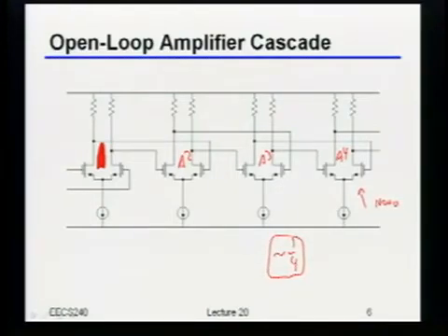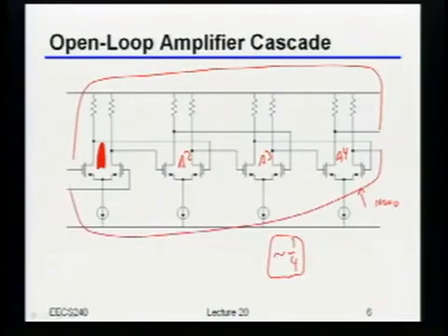My delay, trust me, is going to be larger, which means that doing something like this is probably not a great idea unless I want an oscillator. But for a comparator, that's fine. All I need is just to get enough gain and to get the bandwidth that I wanted.